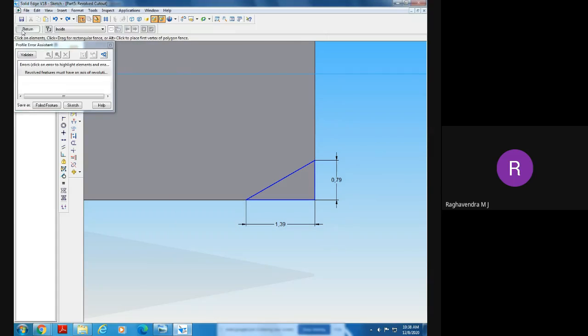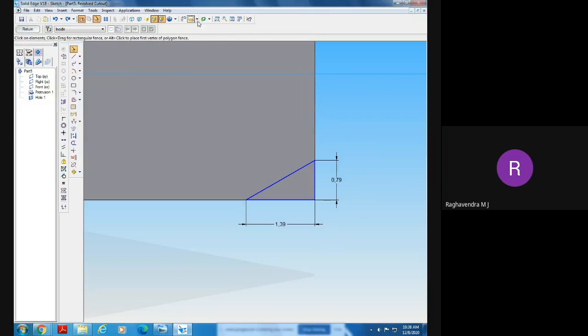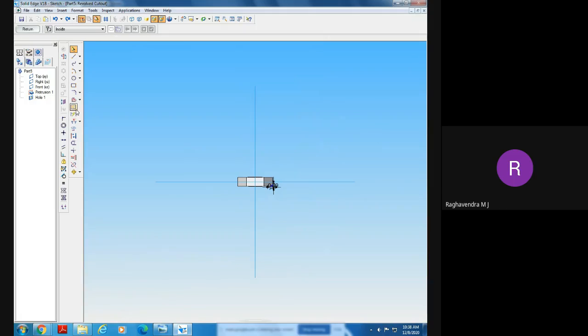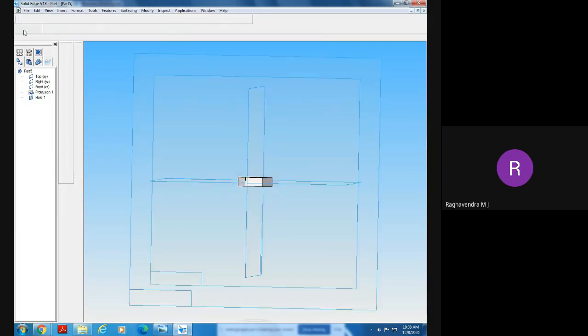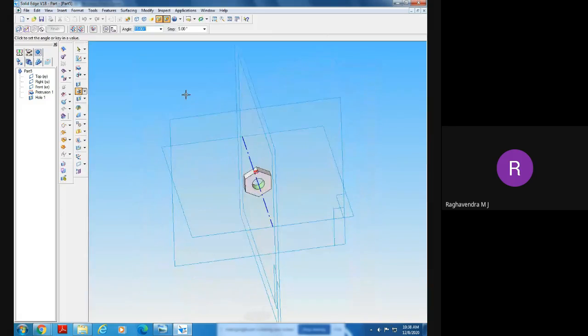Now click on this return. Now we need to select the revolve axis. Click on this revolve axis. There is axis of revolution. Then click on this plane. Now go to return option. Okay, in which angle we need? What is the angle? 360 degree. Click on this revolve 360 degree, or simply you can enter 360 degree. Click on this revolve 360 degree, finish it off.